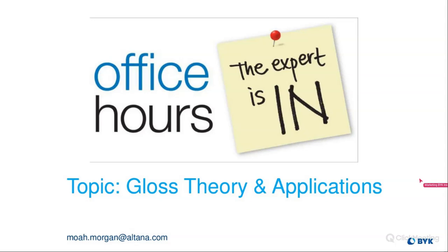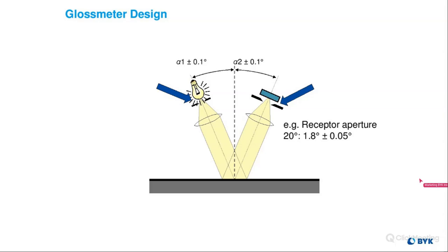Any final thoughts, Noah, or tips that bring this full circle, for people looking at measuring gloss and using it in their day-to-day? Yes. So, remember, we went through this presentation, but the idea of a gloss measurement is very simple. Again, you're just sending light on the sample and then recording how much light is reflected from that surface to get your gloss value. So I wouldn't say overthink it. Just go back to the basics. It's just a simple measurement.